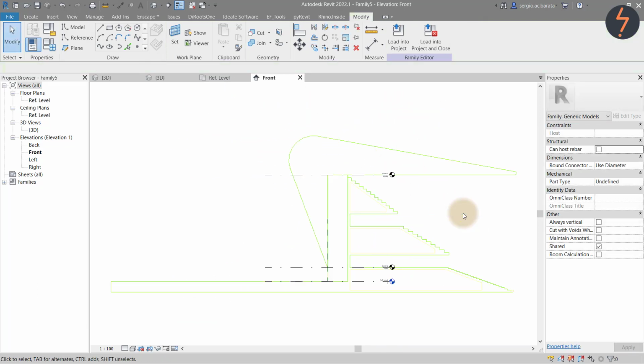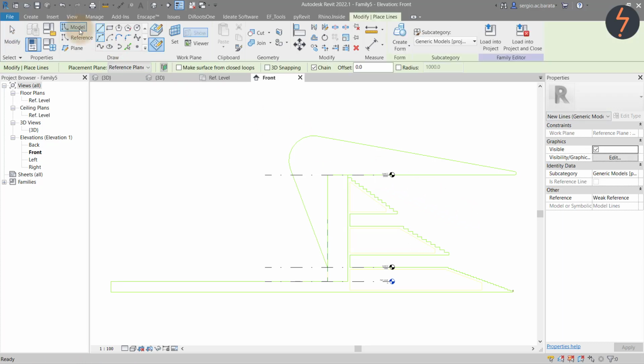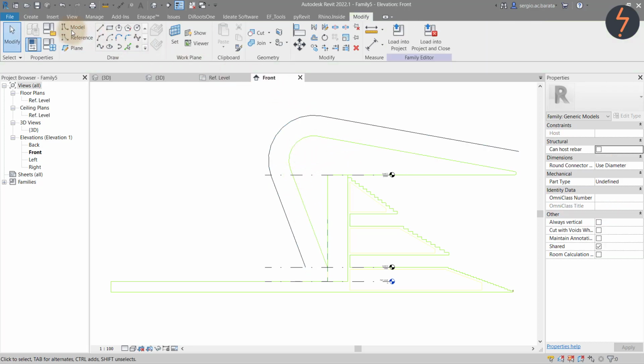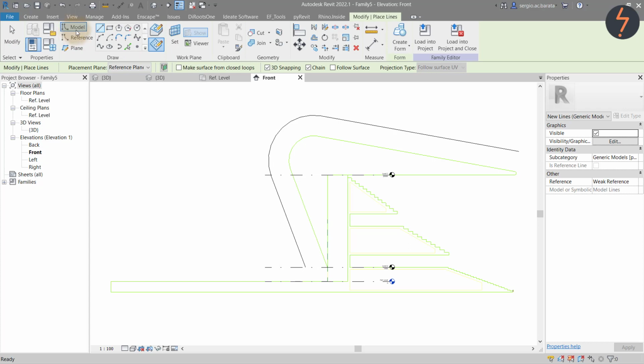Once set, from the Draw tools, pick Model Line, pick Lines, Draw on Plane, and then pick the roof lines on the CAD import as shown. Once drawn, move up to the options bar and find Offset. Set the offset value to 5000 and notice the Draw tools are still selected. Now click the previously placed model lines.